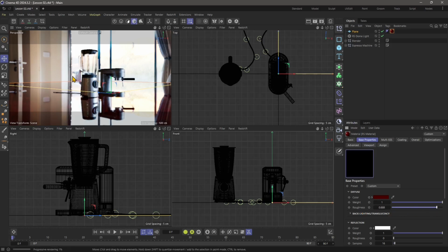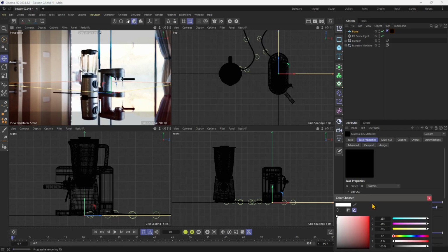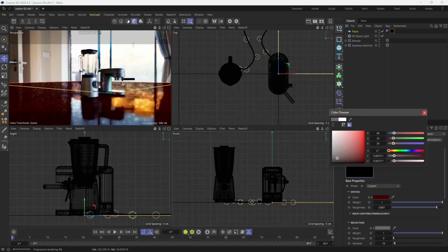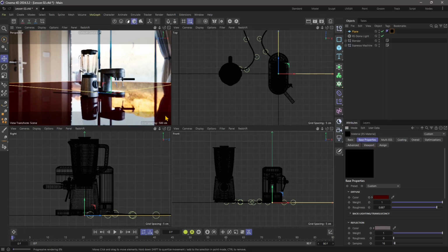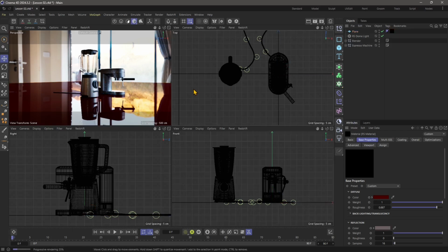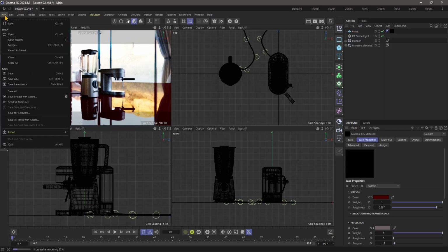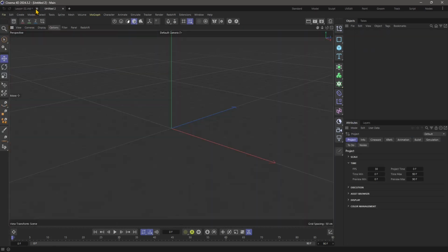And here I want to adjust also the material of the plane that I'm using, because I'm going to increase the roughness and perhaps decrease the reflection using a darker color here. So you can see it's a little bit different. And we're going to come back to the materials, to the lighting more and more in the following lessons. So I'm just gonna show you that you can make an extremely good looking rendering real quick by just using the HDRI and the dome light. But we're gonna talk about the other lights in this video.